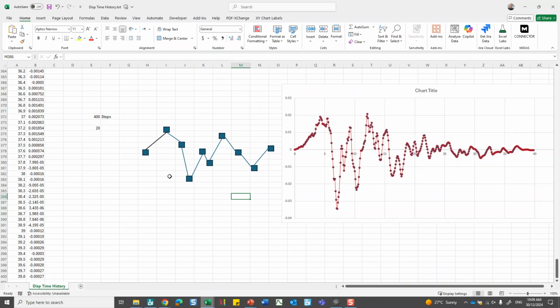PLAXIS will not see this during the calculations, but PLAXIS will see this, which has deviated dramatically from this detailed shape. And as such, don't expect that you will get correct results from this. So what is the alternative? Like I said, there is a trade-off because the execution time can be significant.